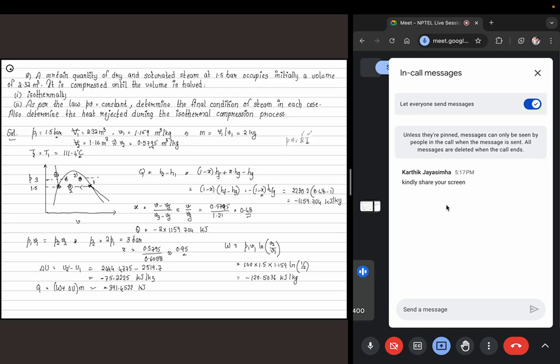So just like you see when we use the steam tables here, though it was an isothermal process, because of the phase change we ended up in a constant pressure region instead of moving to a higher pressure. So this problem is just to reiterate the fact that whenever you have these two phase situations, look up the tables. Don't use the ideal gas law. You're allowed to use the ideal gas law only in the superheated region, not inside the dome. That's the main conclusion that I would like you to take from this particular problem.